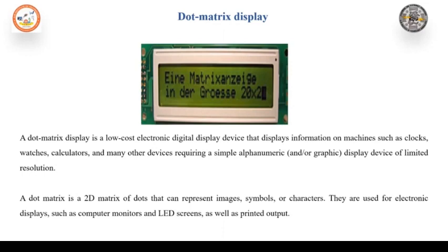The dots may be square or round with 0.4 mm side or diameter. That is, LEDs and LCDs are used for display of dots. Please make note of it. The 5x7 dot matrix format is most popularly used in LED arrays and CRTs.